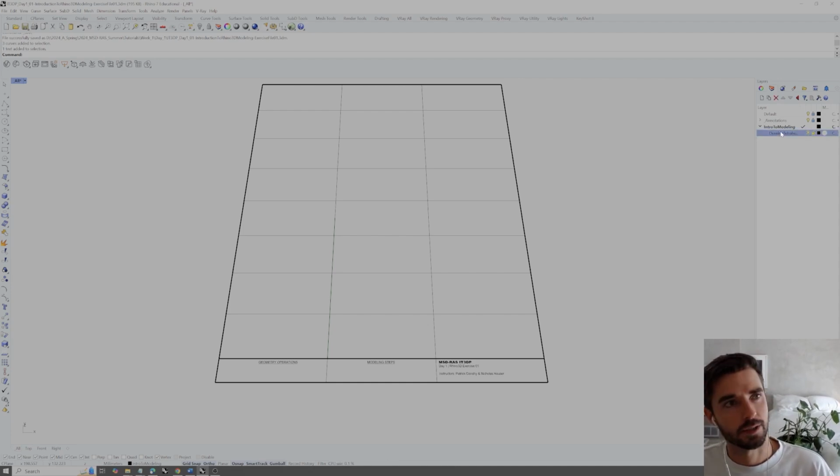So we'll have a layer Drawing Tetrahedron, and then inside of that we'll make additional sublayers, which we'll call 01, 02. I don't know exactly how many steps we'll separate this out into, but let's just say 4 to start. So Drawing Tetrahedron, and then we're going to step through each of these steps. So I'll double click into our first one so that we can make that our active current layer.